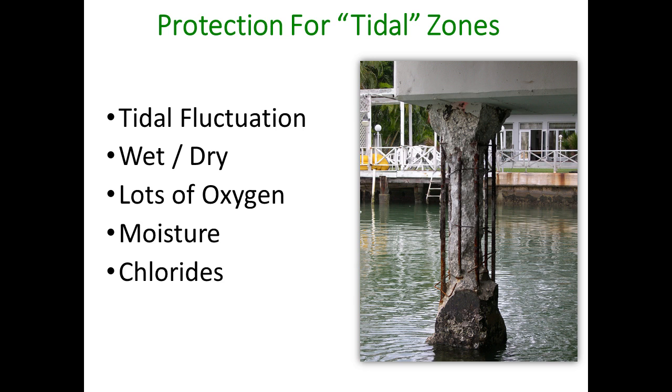And so you can see here, obviously this is where the tide on the picture on the right, this is where the tide's going up and down, and you can see the corrosion that's taking place. And I'm sure everybody's kind of seen this. You get that hourglass shape on these concrete piles. And this can also happen on steel piles as well. This is also an aggressive environment for steel piles.